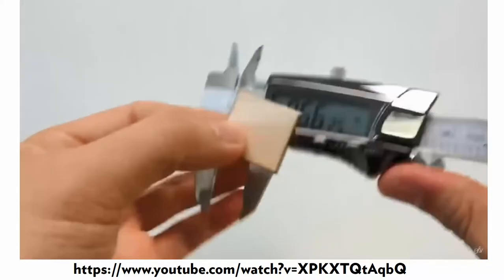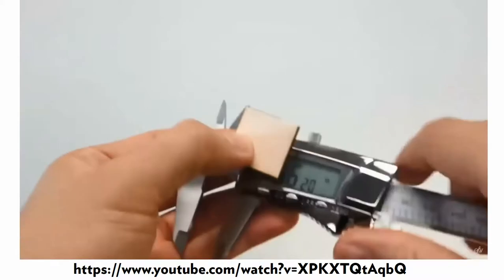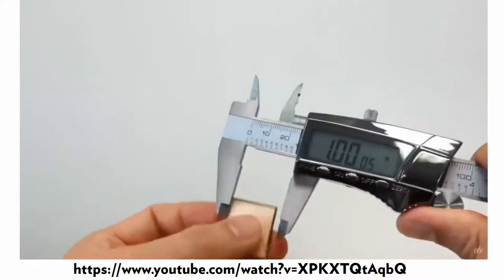So how can you figure out your kerf? You just need to make some test cuts. I make 5 1-inch squares and circles that are 1 inch long and 1 inch in diameter in my cutting software, and then I cut them. You then just take these and measure them and take down your readings.